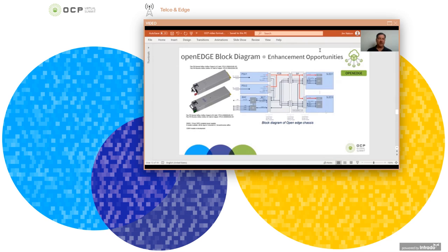So the input connector on the DC is a very specific Anderson connector, and some people may be used to seeing lugs or different types of ways to connect the minus 48 volt input, but that's how you can distinguish between the two, by the input connector. They both interact with the rack management controller via PMBus, and they can communicate that everything's fine, power is okay, and enable the system to be able to turn on.